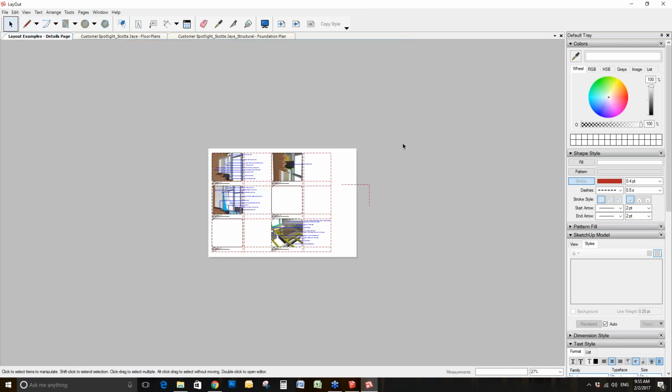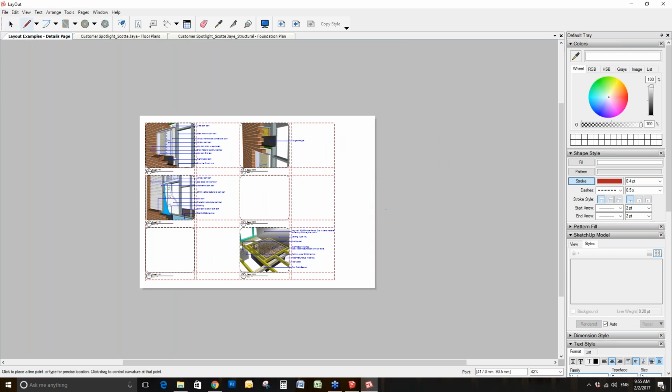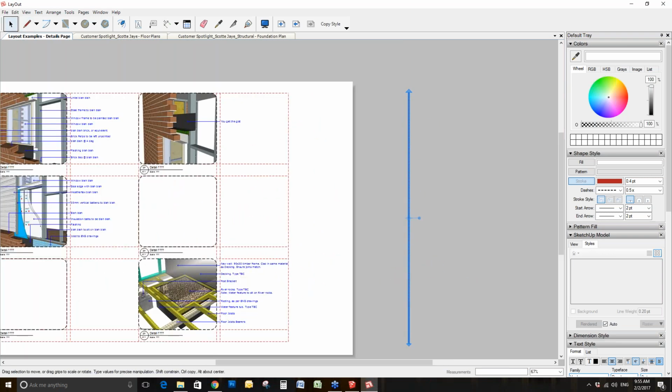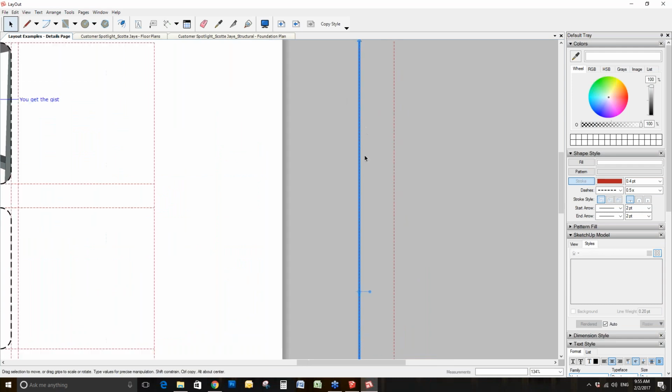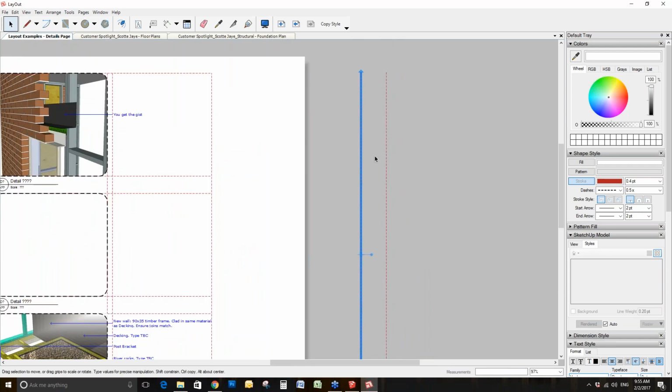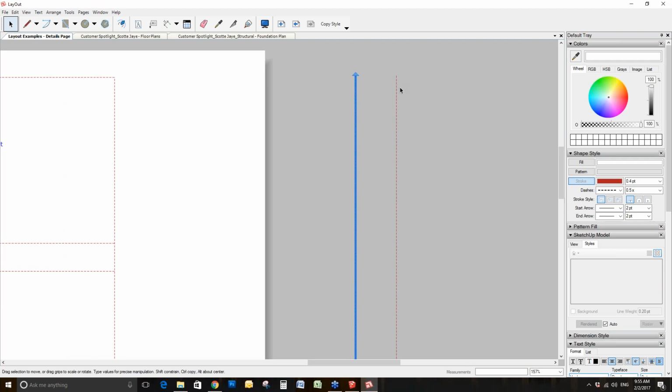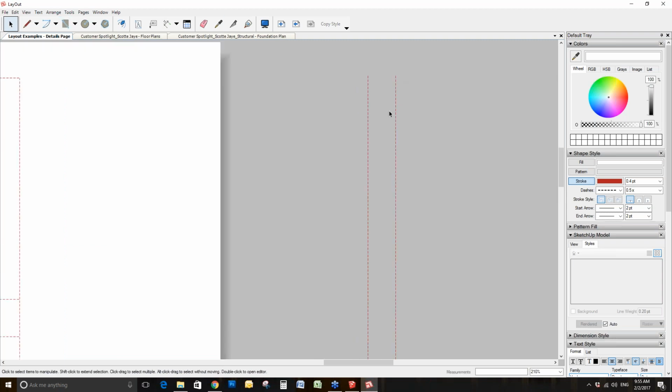So to set up the grids, all I did was space them. I just went, okay, I know that this is the extent of the drawing that I want, depending on the paper size that you're using and so forth. Also, in layout, you can copy and move things and draft them purely using layout to scale. The only difference is you can't draw 1:1. You have to know the scale that you want it to be in. So if you're drawing it 1:100, after you've moved it, you then type in the distance that you actually want it to be to read at 1:1.